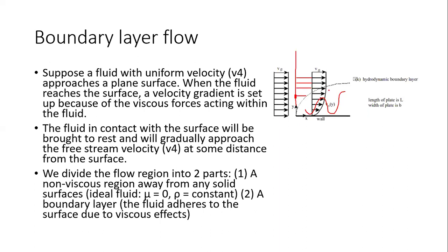And we said that when we are above the hydrodynamic boundary layer, we can assume that we are working with ideal flow. So you realize that if you look at the velocity profile, you can see that the velocity reduces. You can see the arrow here is smaller than the arrow here. But when it gets above the layer, the arrows are almost the same length. So the velocities are literally the same at those points. Is that okay? So that's what the boundary layer is.